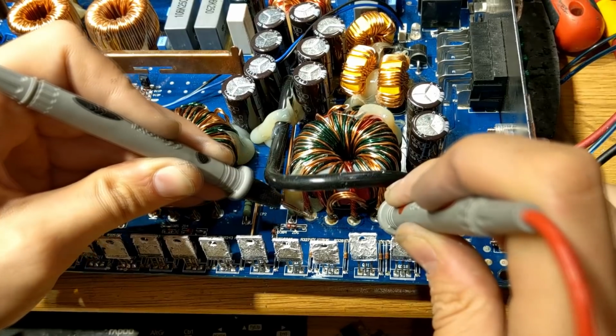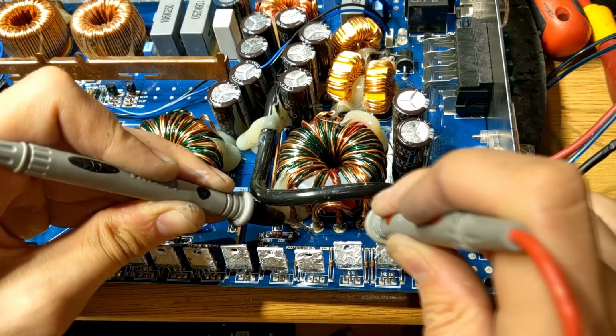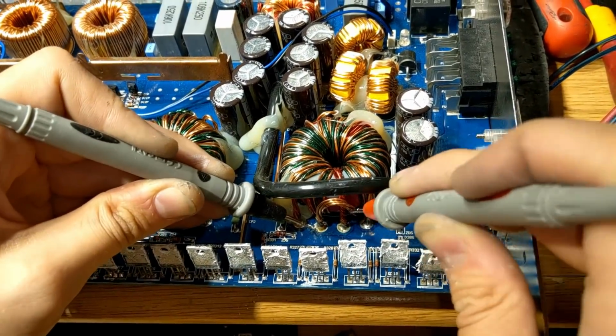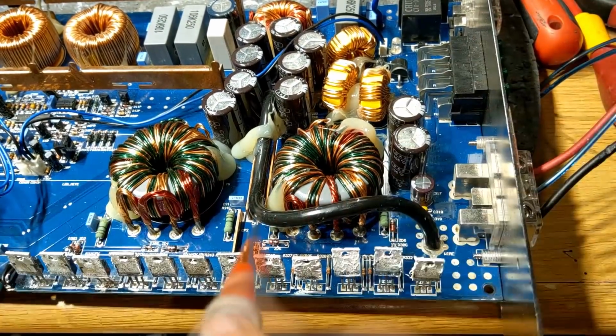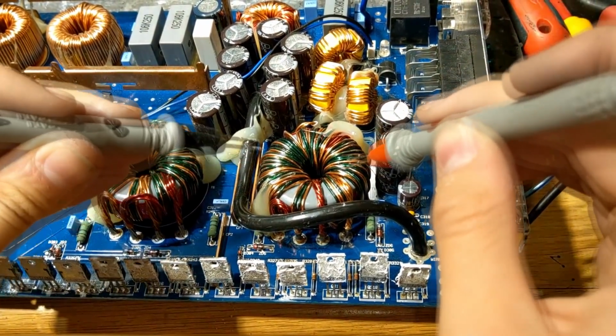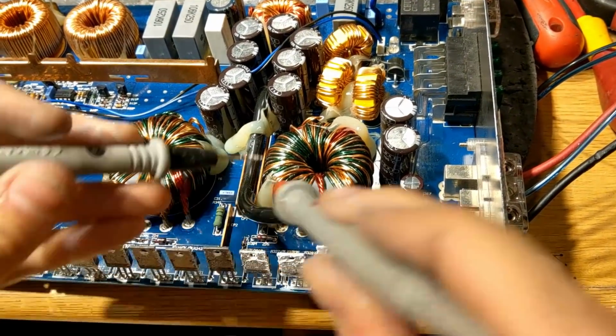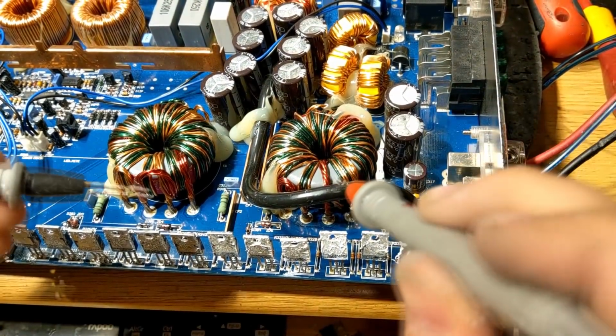See, these aren't connected to each other. The 2 red ones, beep, they're connected, but the 2 gold ones, they're not connected to each other. Therefore, there's a break in this wire somewhere around this transformer. So I'm going to have to pull this off and see if I can repair it. But if I can't, then you can't get these anymore. I'll probably have to rewind this whole transformer, which will take a long time.